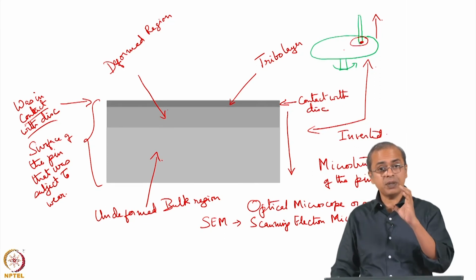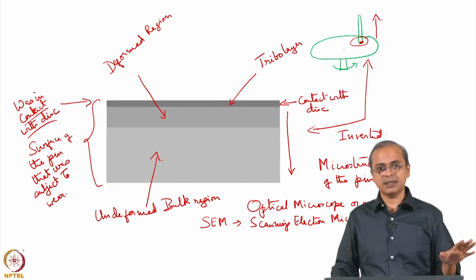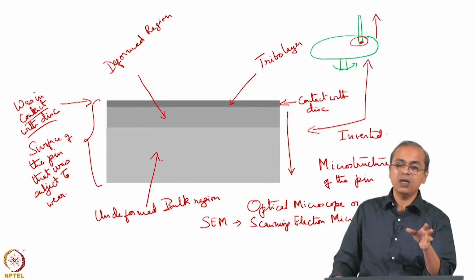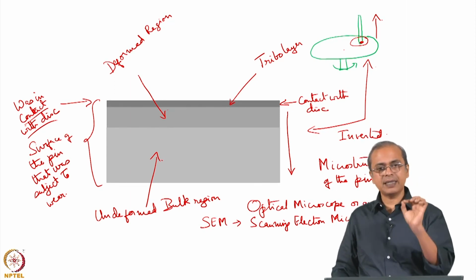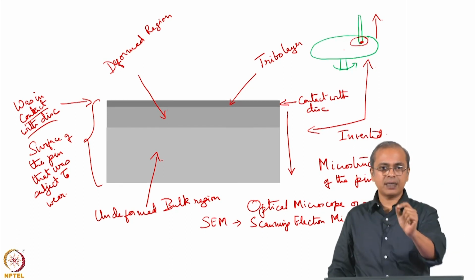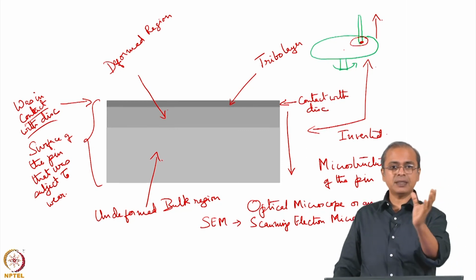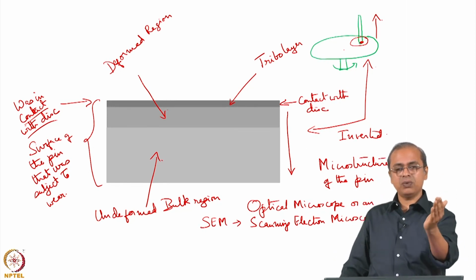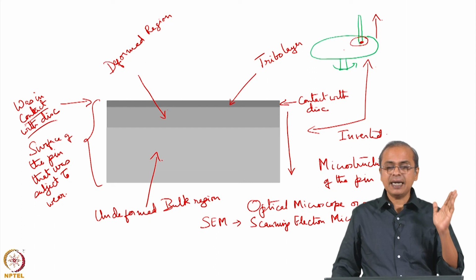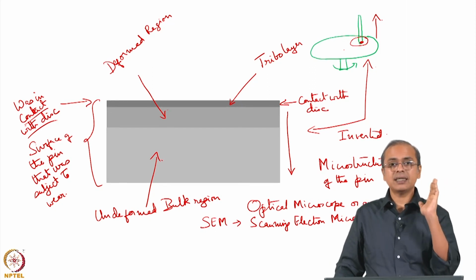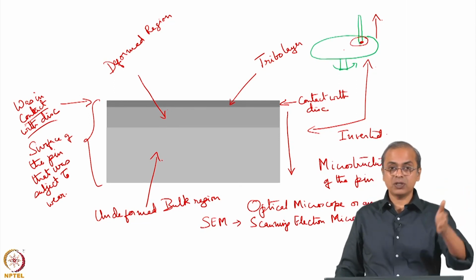And so for example, if you have a pipe with just a smooth liquid flowing through it, then the interior surface of the pipe is not scratched. On the other hand, let us say you have some muddy water flowing through it, then you have a lot of mud particles continuously bouncing off the pipe as they go through, especially if it is a turn. If you have a straight pipe and then it makes a turn, then at the outer periphery of the turn, those particles are continuously rubbing that surface, scratching that protective oxide layer, repeatedly damaging that oxide layer and forming fresh oxide at an interior layer.